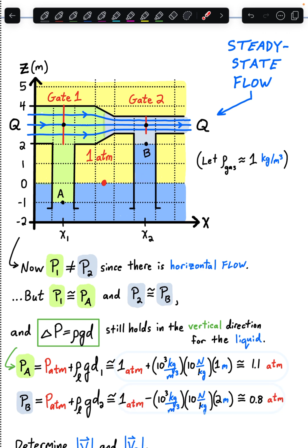So putting those values in, careful, we gotta be careful here about which is the higher pressure. Here, we're expecting that this is the higher pressure than at B. Since the gas pressure dropped here, water rose in this column due to the air pressure here being lower than the outside pressure. So the pressure at B is actually lower than the pressure out here at this point. That's why the water has risen in this column. So I've got to fix my sign right here in the equation. The pressure at B is lower than atmospheric pressure.